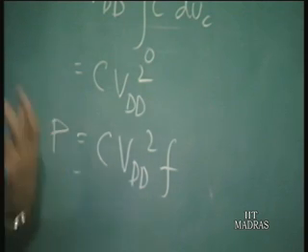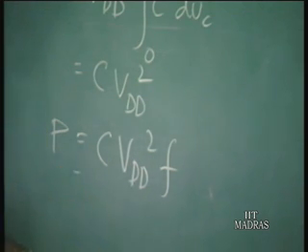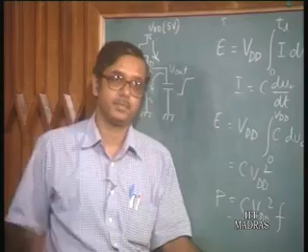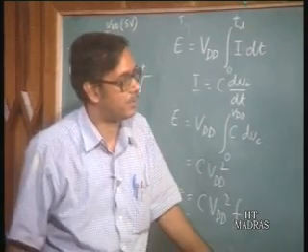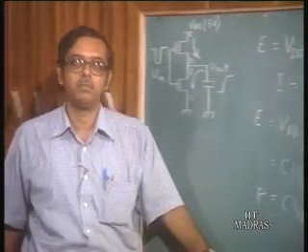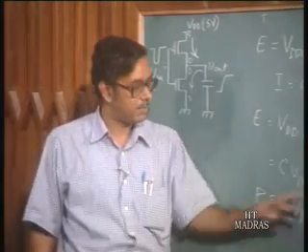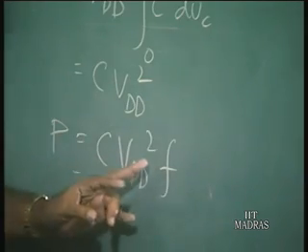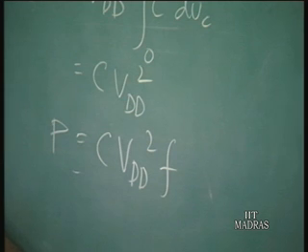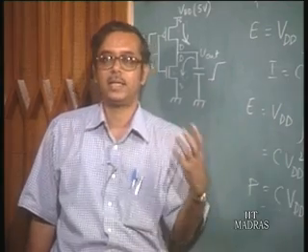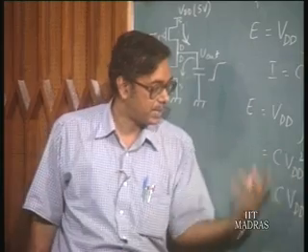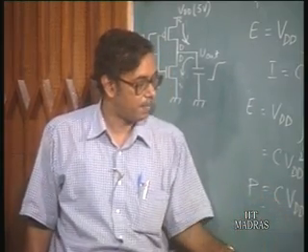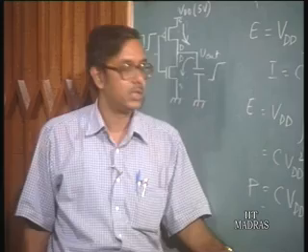This power dissipation depends on the frequency. So if the input frequency is high, the power dissipation will increase. It is linearly dependent on frequency. So it is actually sort of a myth that the CMOS power dissipation is very low. In fact, the CMOS will have a large power dissipation if the frequency is very large. Only thing is that the static power dissipation is 0. That is, if the input is not changing state, the power dissipation is 0. But if there are transitions, then there is going to be a power dissipation which is linearly proportional to the frequency.